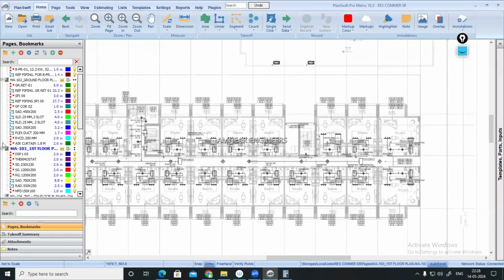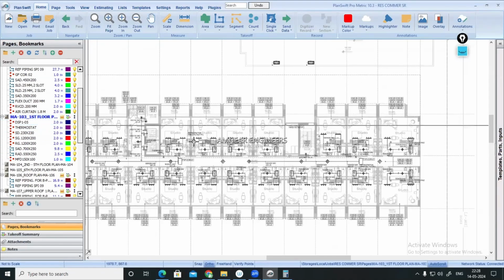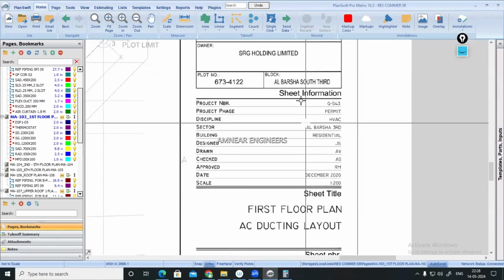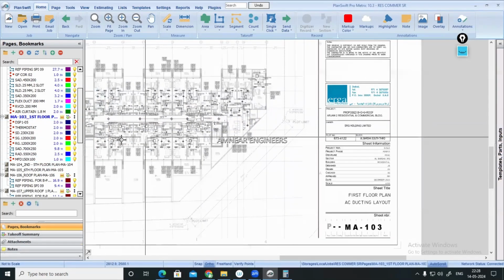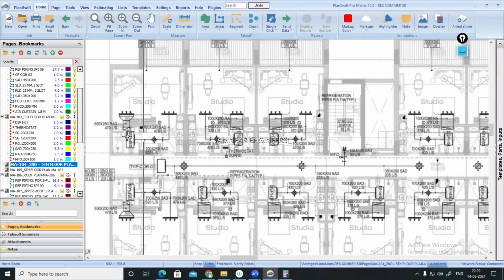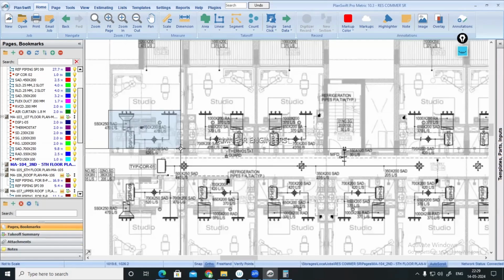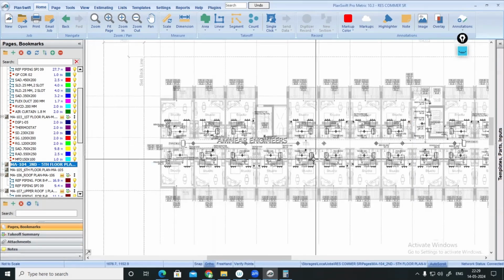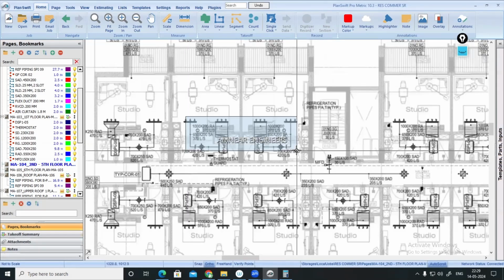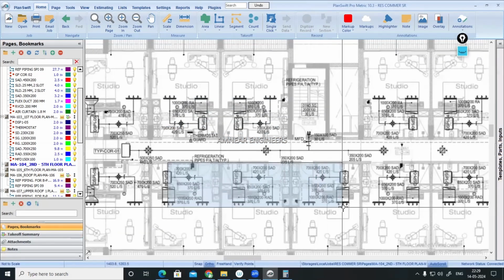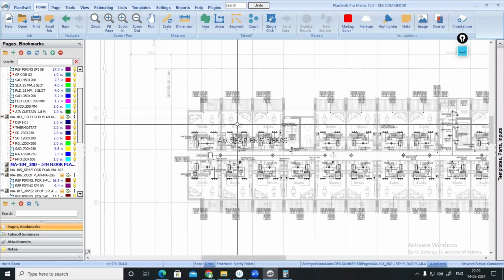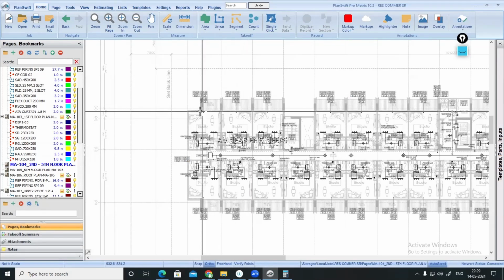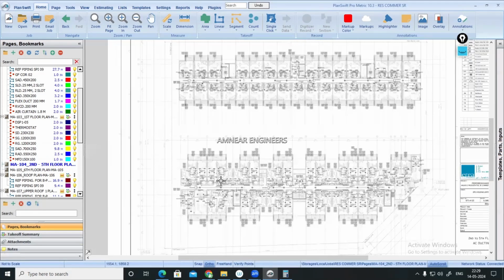Okay, no confusion. The same way, this is first floor. What quantity you are having in the first floor, the same quantity you can continue, because first floor typical only, all the floors. Second floor, if it is typical to first floor, then you can multiply. Anyhow, second floor to fifth floor, this is typical only for this project. That's why, anyhow, 1200, 1200, 700, 200, 700, 200, 700, 200, 700, 200. Typically only this one. One or two areas you have to take, and after that you can multiply the quantity with every other quantity. Okay. Like that it will be easy.